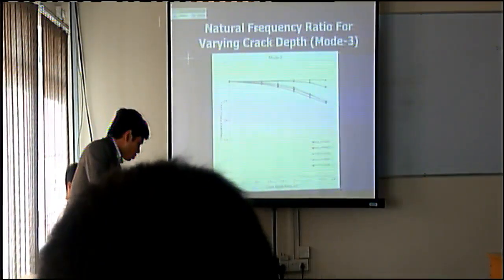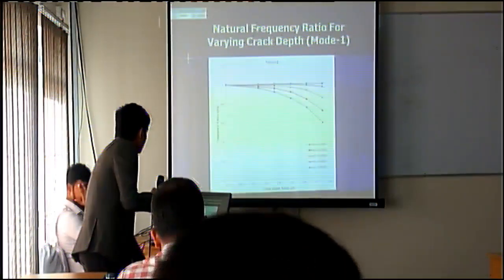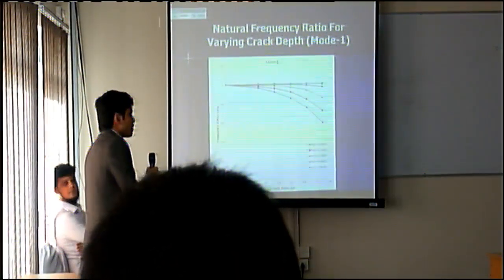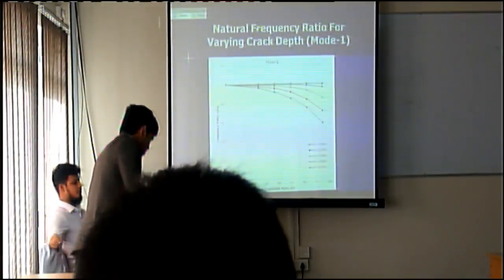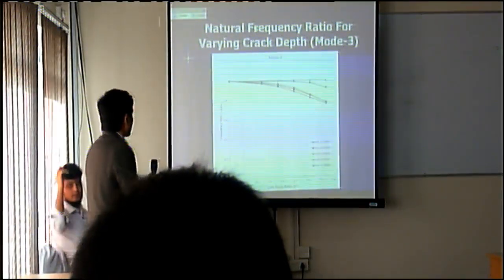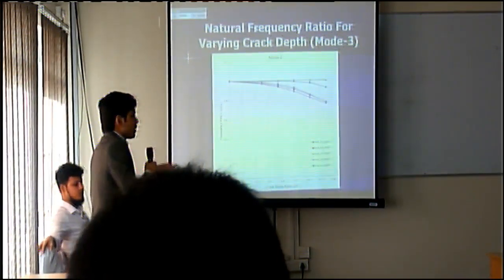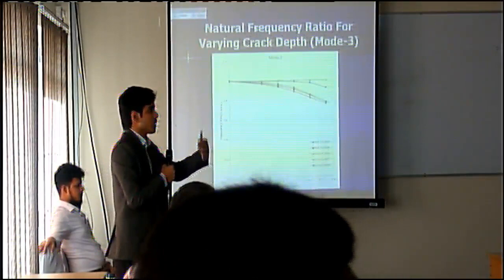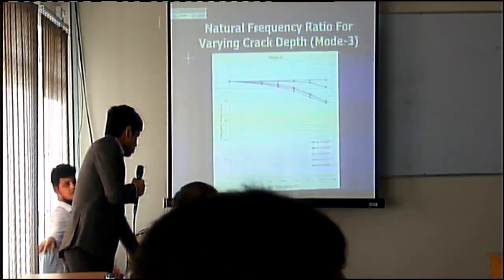So for mode 1, we get that if the crack is located at the free end, 0.833, the frequency is not changing. But for mode 3, if the crack is located at 0.5, the frequency is not changing. So it depends on mode shape, in which mode the beam is vibrating.